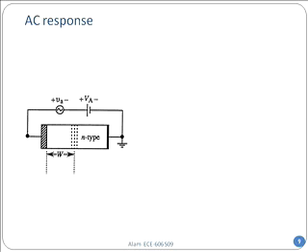This is again a metal-semiconductor diode, N-type, contacted with the metal, the dashed region. You have a AAA battery, that's the V_A, and let's say you have your favorite radio signal, on the order of a microvolt or so, and that is the small v_a. As the bias is modulated with that small v_a, sometimes it's a little bit more forward bias, sometimes a little bit less, so it's oscillating, right? The net bias is oscillating, and therefore there will be a current that oscillates in response.